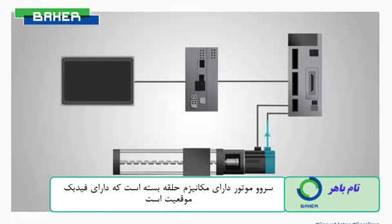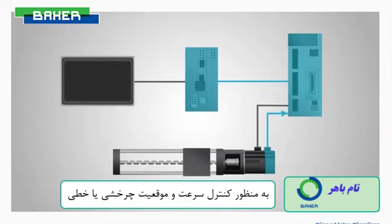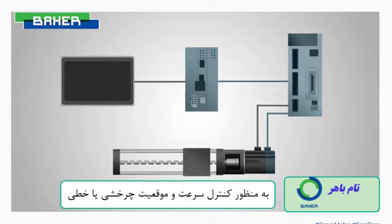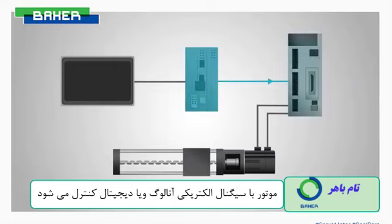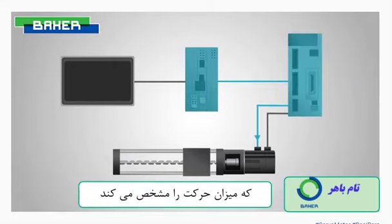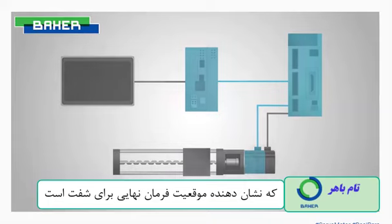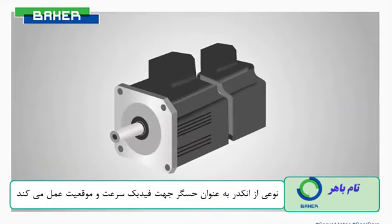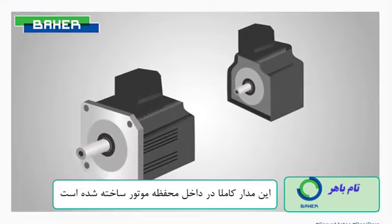The servo motor is a closed-loop mechanism that incorporates positional feedback in order to control the rotational or linear speed and position. The motor is controlled with an electric signal, either analog or digital, which determines the amount of movement, which represents the final command position for the shaft. A type of encoder serves as a sensor, providing speed and position feedback. This circuitry is built right inside the motor housing, which usually is fitted with a gear system.